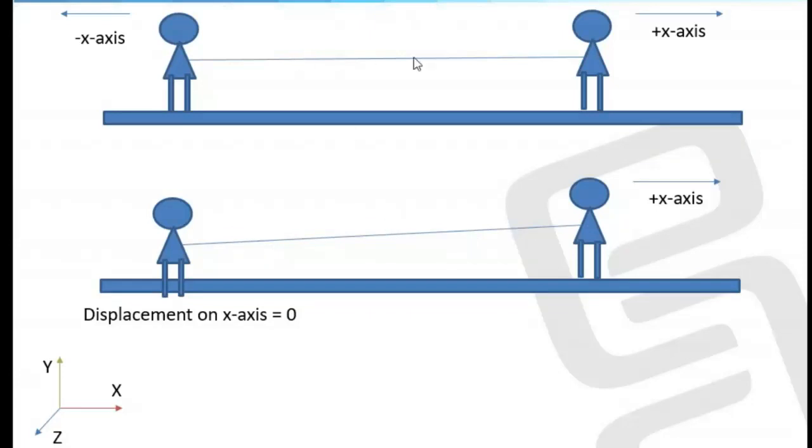So practically the situation is like this, where two people are applying force in opposite direction. In software world, we fix one position of a person and we apply force in another position of the person and find out the values of deformation and stresses. Based on degrees of freedom, you specify where to exactly apply the constraints and on what degrees of freedom you have to make that particular model fixed and free. We'll discuss this in detail as we go ahead of these sessions.